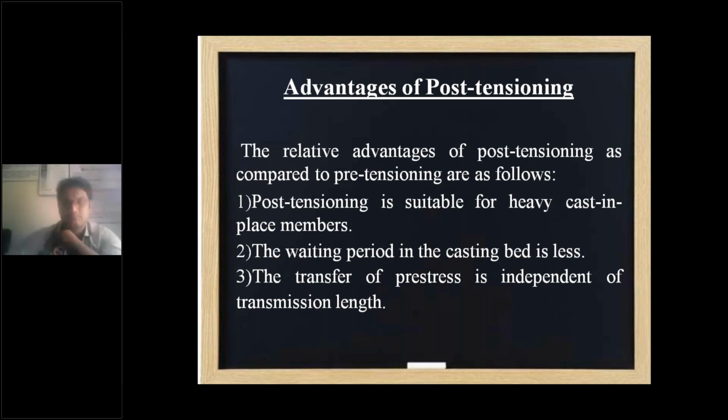And the waiting period in the casting bed is very less. Here you can make use of the bed very easily. Why? Because after casting you can shift the member to the other place and do tensioning. You need not wait for 28 days on the same platform where it will be held up. In that way you can make use of the platform for other elements very easily, because within 3 days you can shift the element to the next bed.